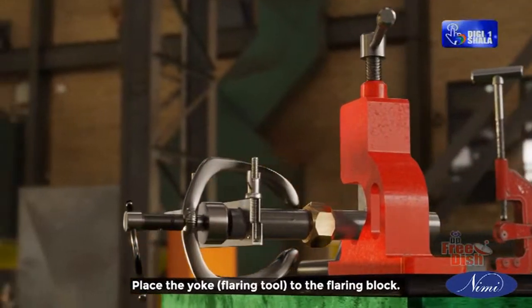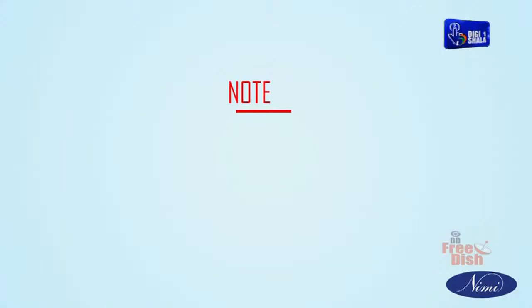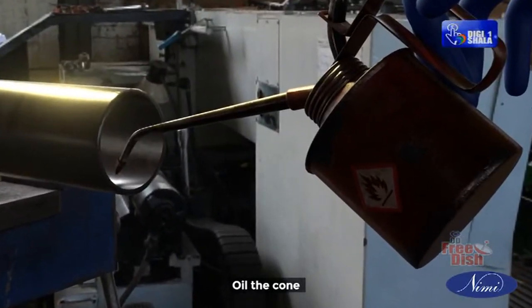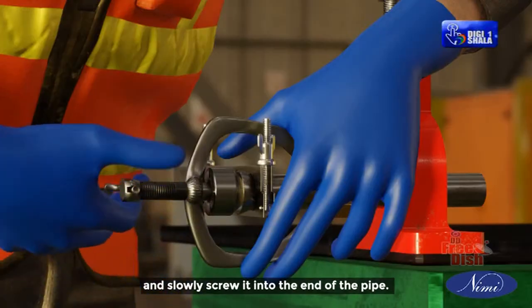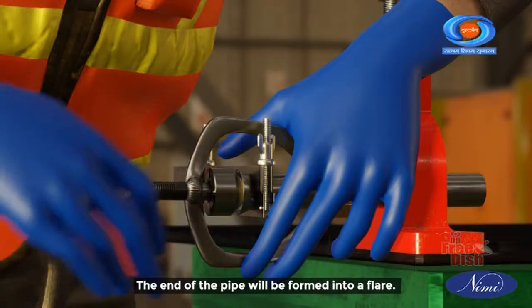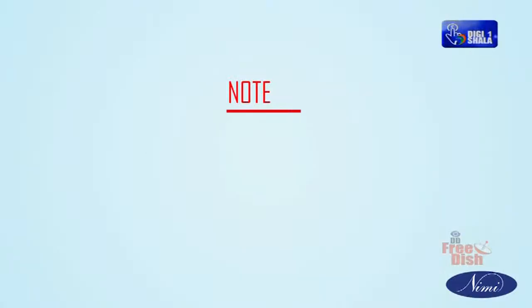Place the yoke, the flaring tool, onto the flaring block. Note: insert the flare nut before flaring. Oil the cone and slowly screw it into the end of the pipe. The end of the pipe will be formed into a flare. Note: do not over-tighten the screws.